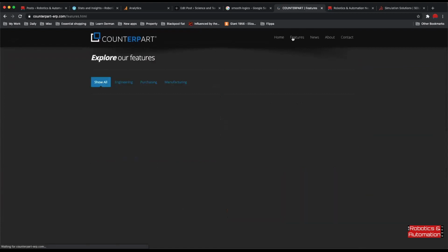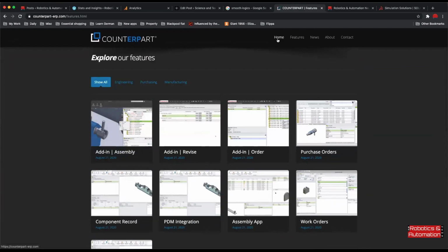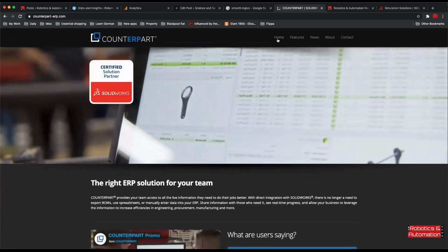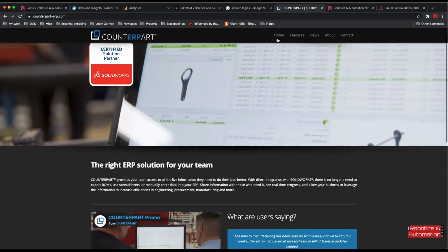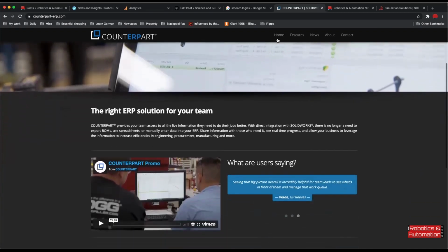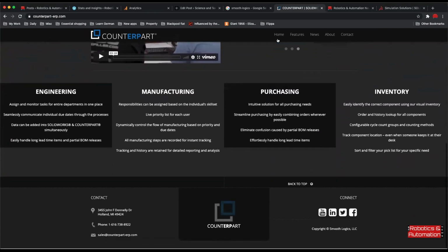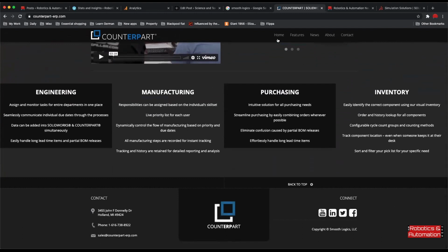So if it's in the food and beverage industry, there's really not any 3D printing that's FDA approved or something that can hold up to the chemicals and the sanitization. If it's in a high stress industry like heavy metal, it's generally not strong enough or doesn't resist enough heat for welding or manufacturing or some of the coatings and whatnot. But 3D printing is very prevalent, especially in the prototyping phase, and especially to try to get a reality on your design.